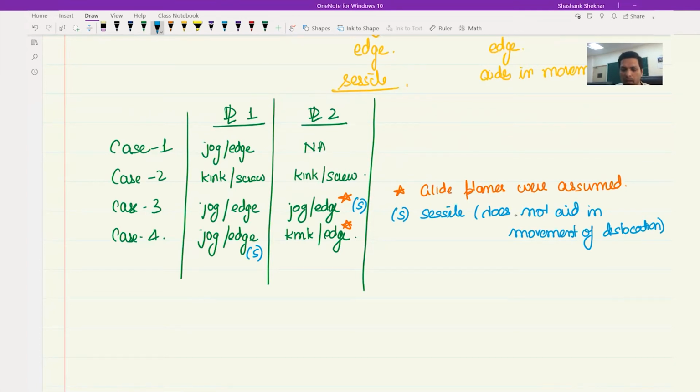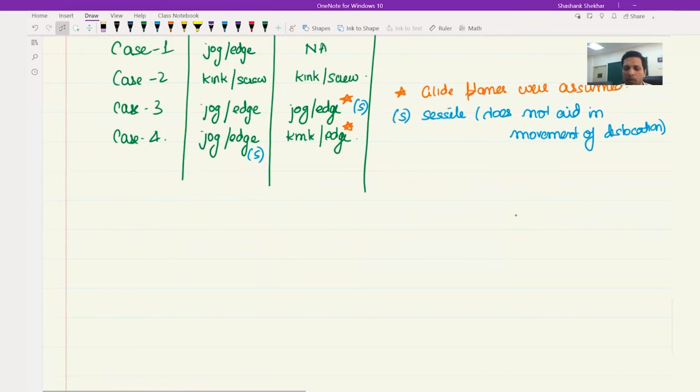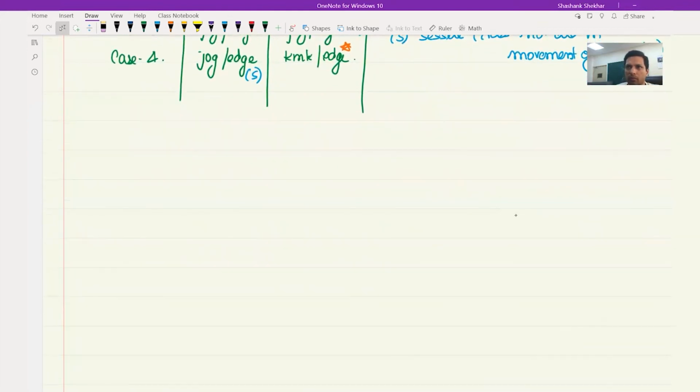So what we see again here is that these can form or can pin the dislocations. And when you pin these dislocations, then when you keep applying the stress, the dislocation length will increase and eventually it will form a loop and loop around, and extra length of dislocation will be formed and it will at one point break away. And then again, the original dislocation will stay there. And if you keep applying, this is how the dislocation density keeps increasing. And the other part that we said is that whenever there is a step formed, there is an energy cost. So what do we mean by that? So let's look at that part also.